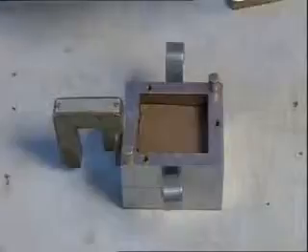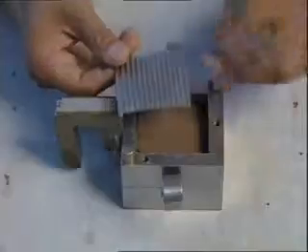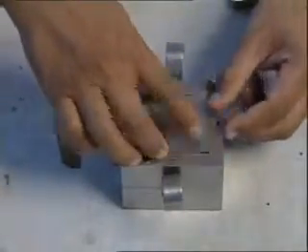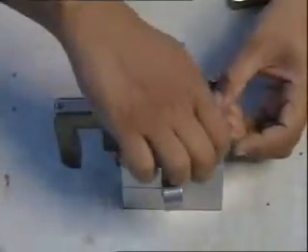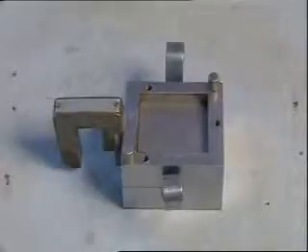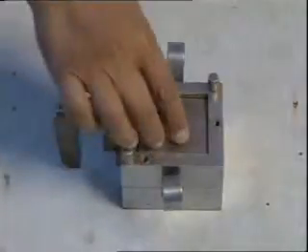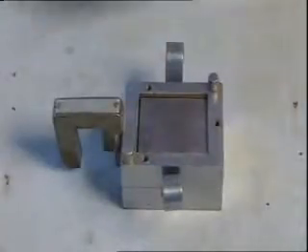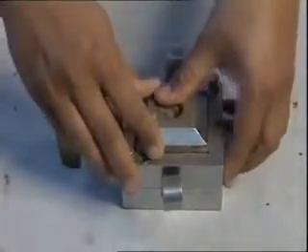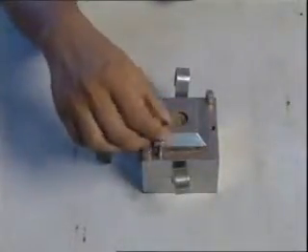Over the top of the soil sample, now place another grid plate without perforations such that the grids are perpendicular to the direction of shear. Slightly press this grid plate evenly so that the grids are buried into the sample. Now place another metal plate over this grid plate. Place the loading pad on the top of the metal plate. Place the adjusting pins in the box.